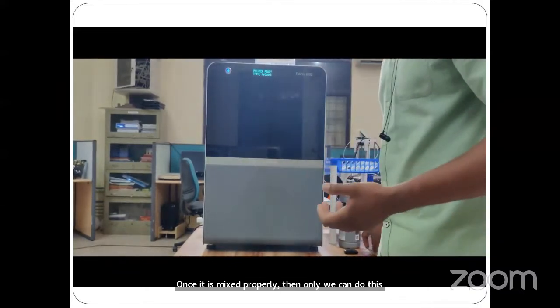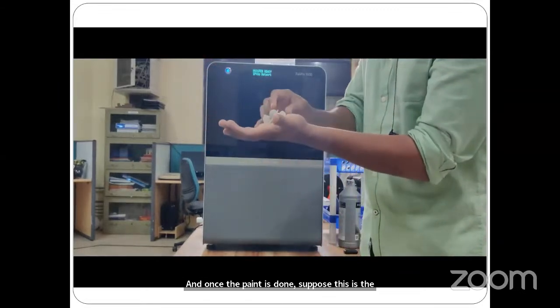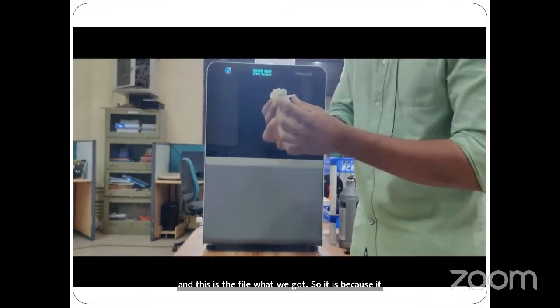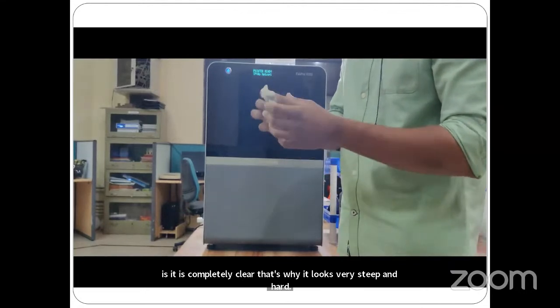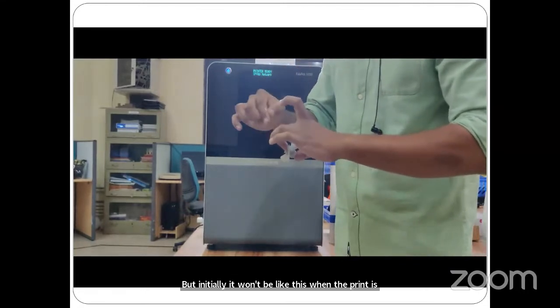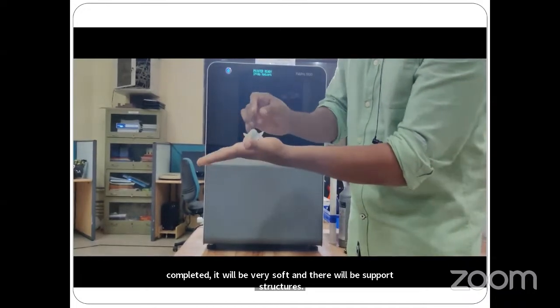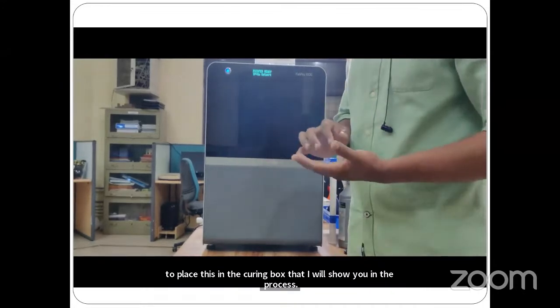And once the print is done, suppose this is the output and this is the file we got. Because it is completely cured, it looks very stiff and hard. But initially it won't be like this. When the print is completed, it will be very soft, and there will be support structures. We have to remove those support structures and place this in the curing box that I will show you in the process.